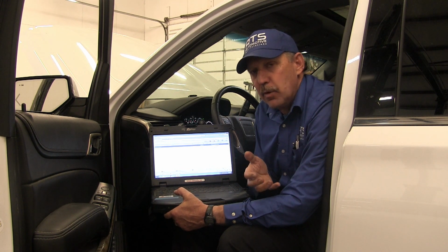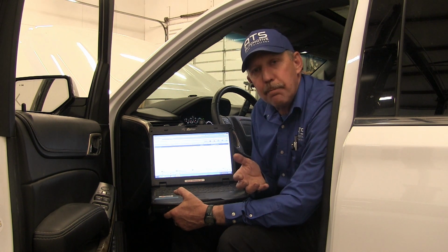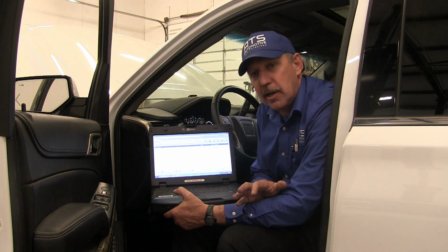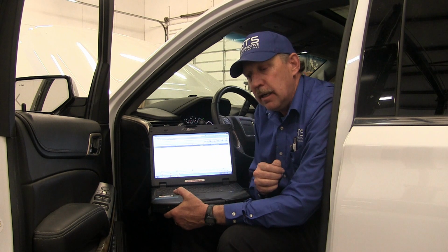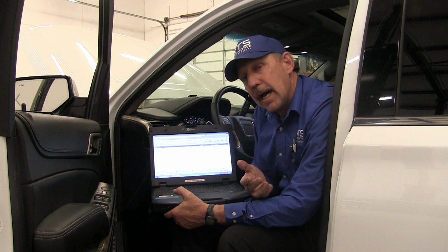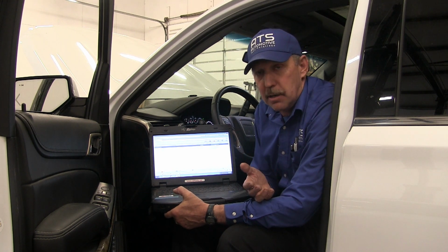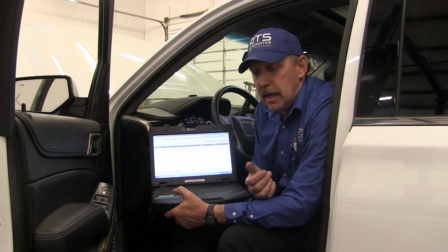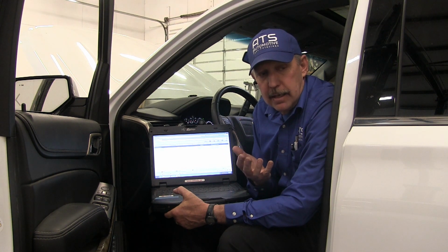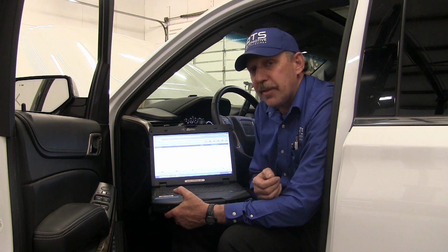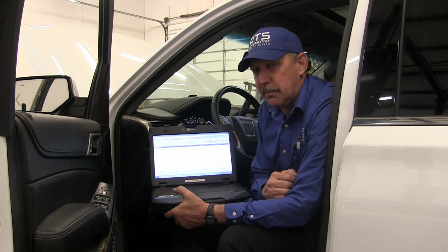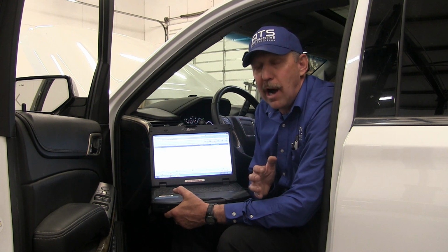So this camera was actually able to go through a complete diagnostics and self-calibrate, which is again a safety critical system, which makes me think that this is a real intermittent problem for the communication failure. We can communicate with this module. We know we have some communication failures here, and the failures are in history or they've passed and failed, which means that we're probably dealing with something that's intermittent, is what I'm thinking by what the scan tool data is displaying and telling me.